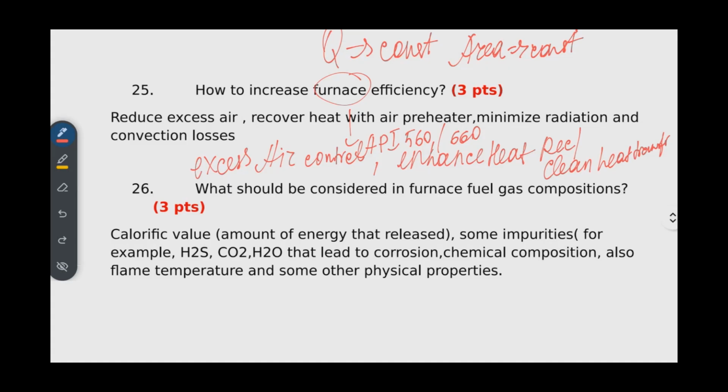So for the furnaces, in order to increase the lifetime of your furnace, you need to have a clean heat transfer surface area. It's a bit hard to achieve because we are in a hydrocarbons environment and we are discussing very heavy hydrocarbons even sometimes. So that's why it's a bit hard, but we need to follow this.